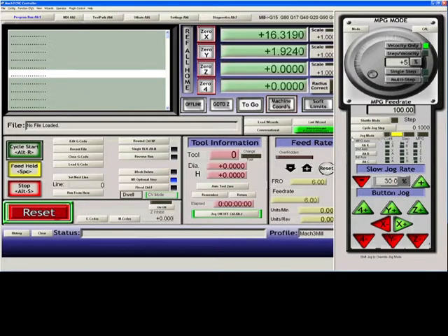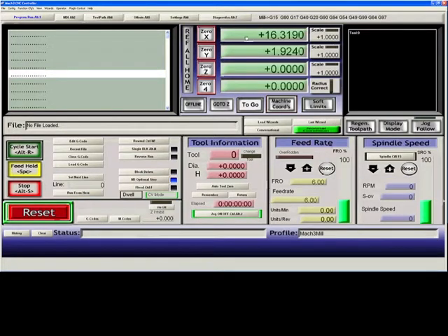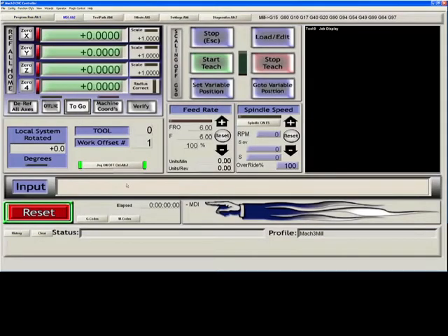The next question that often comes up is, how do I know that my axes are accurate? If I zero my X movement, and we go to the MDI screen, and we say G0 X5, you can see that the XDRO moves us to 5.000. This is correct, but many people find that their system did not move 5. In actual fact, the axis may have moved only a 1/4 inch, or it may have moved 10 inches. This is all set up by the motor tuning steps per inch.